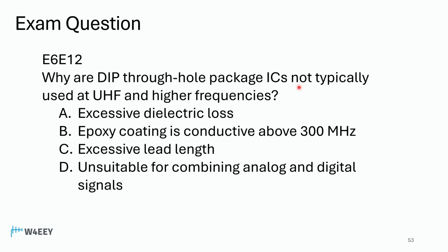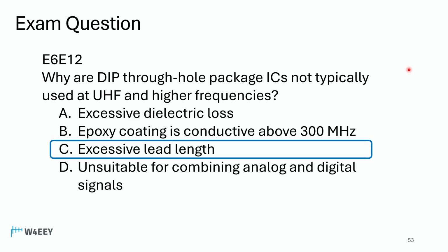Why are DIP through-hole package ICs not typically used at UHF and higher? Charlie. Yep, excessively long leads. They don't look like they're very long, especially when they're soldered on the board, but surface mount is much shorter.